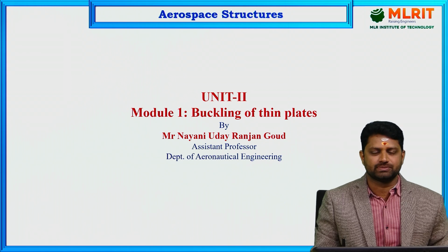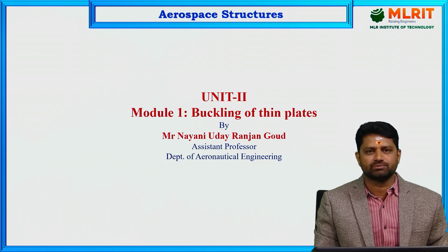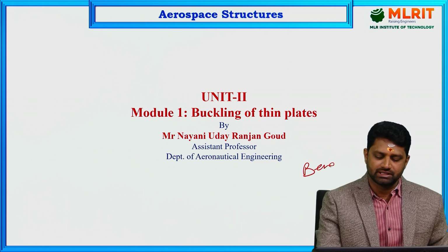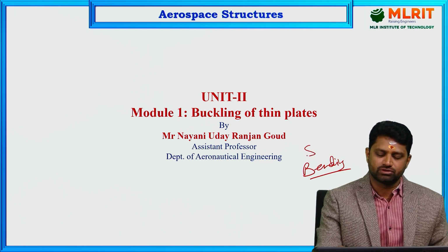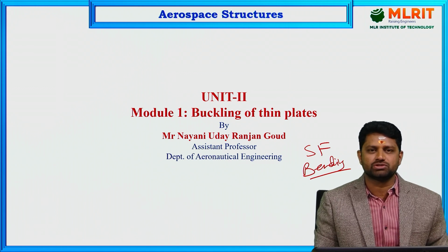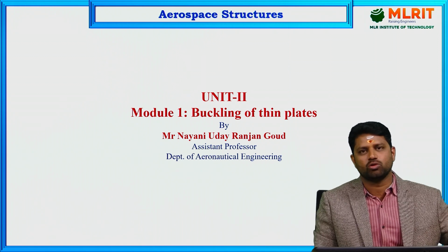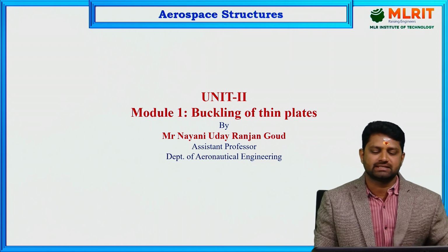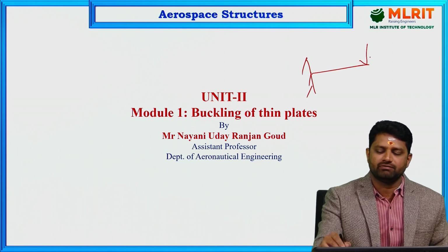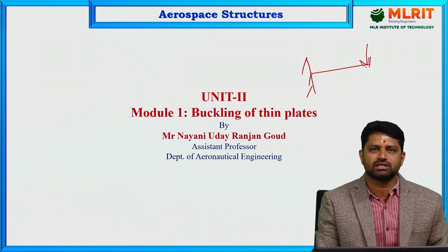of thin plates. Now, previously in the mechanics of solids subject, we have a term called bending. Whenever you see this bending, shear force and bending moment, we used to draw shear force diagrams and bending moment diagrams. So basically, let us have a small example, for example, a cantilever beam, and in this cantilever beam, we need to draw the shear force and bending moment diagram.